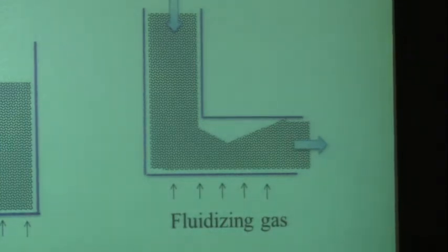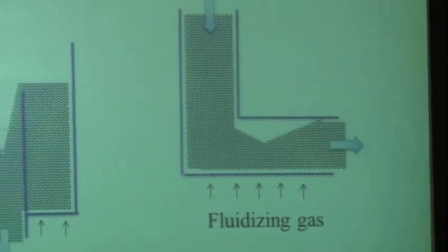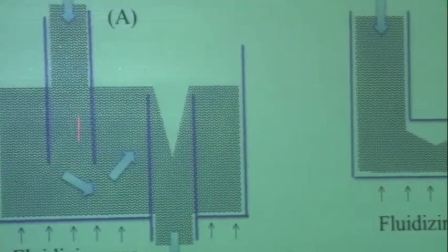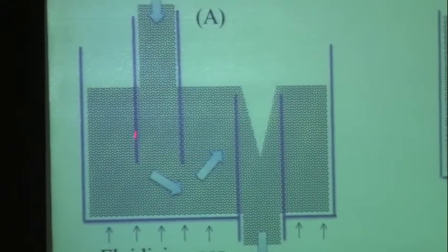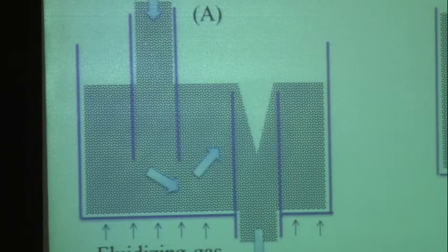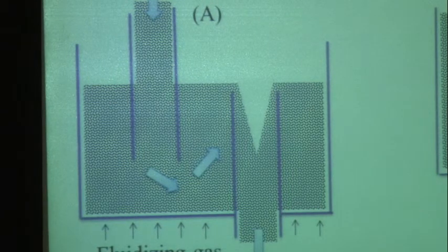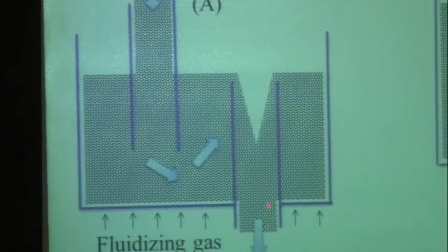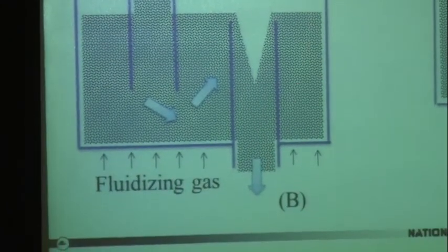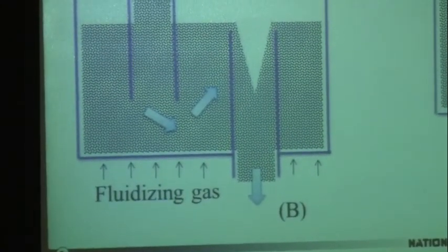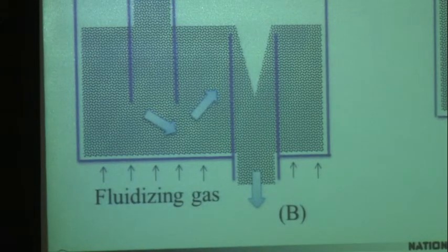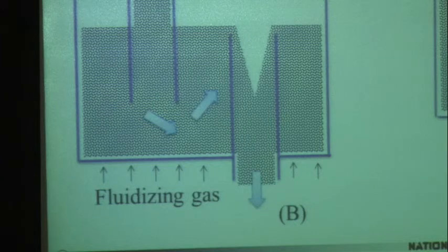And then loop seal, all right? This was shown on that diagram. This is just handy to be aware of. You have the flow coming down this way. There's a bed of material. Think of it as like a liquid, in that region. It just fills up to this point and then spills over. So now whatever's going down here is isolated from whatever is up in here, which is how we keep the CO2 separate from the airstream. That loop seal, got to have one of those. All right, they too follow a design for fluidization.